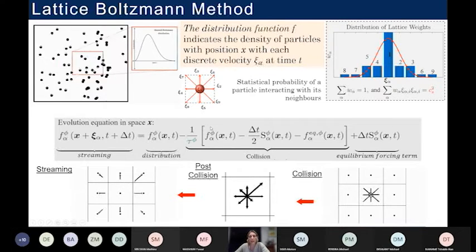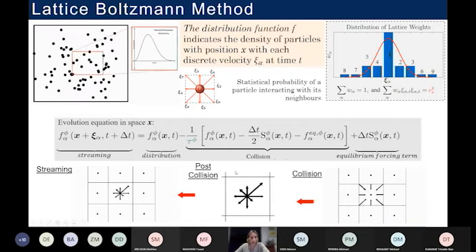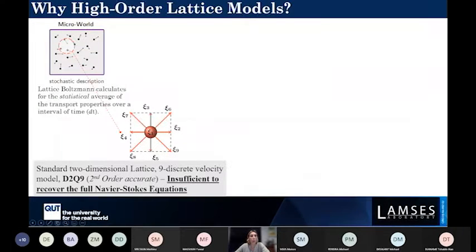That's really the basic fundamentals of the Lattice Boltzmann approach. What I'm interested in is the most common, the classical standard lattice structure, what we call a D2Q9. So I'm only focusing on 2 dimensions. D2 just means that's a 2D case, and Q9 means that we've got 9 discrete velocities associated with each particle, as represented here.